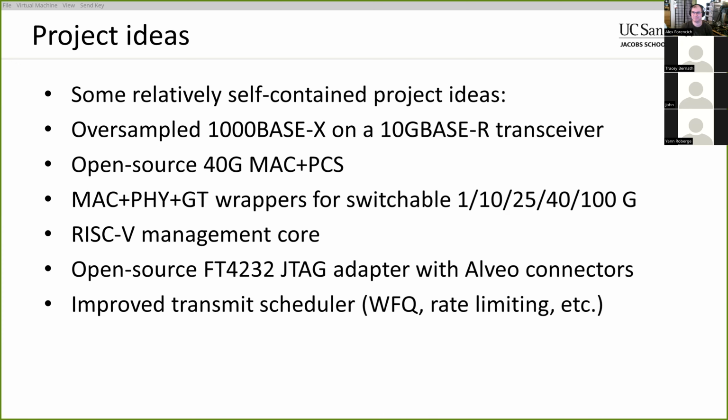They ask you to flash a bit stream over this static part of the chip, and then they have some extra steps to flash all of the onboard MicroBlazes that they have on top of there. Because those all load their code out of flash. I'm not sure where they load their code from.